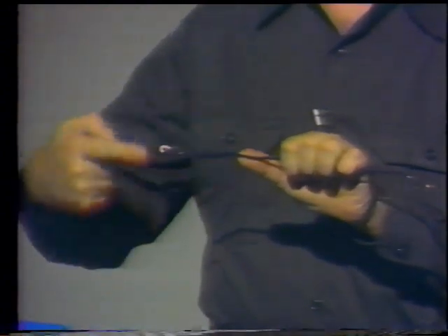Now, there's a rule you can follow so that you'll always know which way the magnetic field will flow. You can use this rule instead of a compass. It's called the left-hand rule, and it'll come in handy when you're studying motors and generators. It's an easy way to remember the relationship between the direction of the magnetic lines of force around a conductor and the direction of current flow. The left-hand rule works like this. Imagine that you're holding the conductor in your left hand with your thumb pointed in the direction of the current flow. Your curled fingers are then pointing in the same direction as the magnetic lines of force.